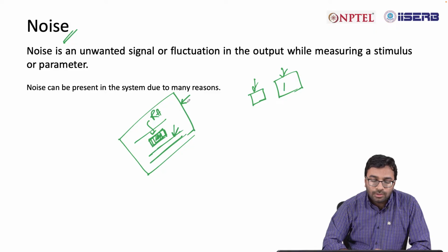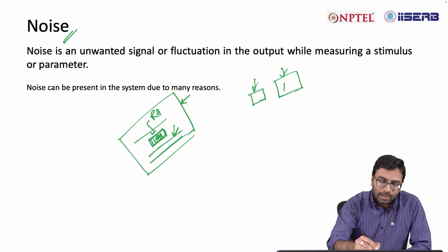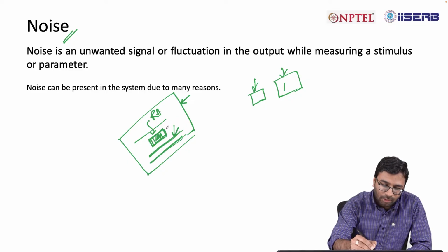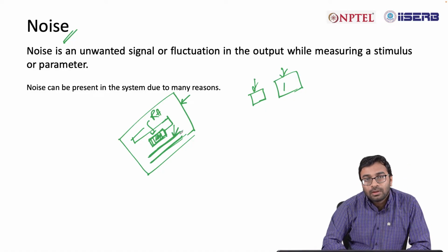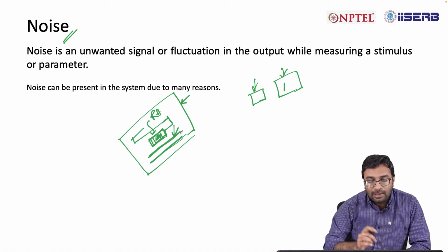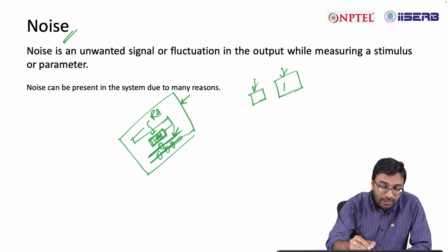Okay, so you placed your sensor somewhere in the middle of the PCB, and then there are multiple connections around that device. Those connections, or those conductors, also carry current, and when those currents are flowing through those conductors, they create a certain sort of magnetic field.